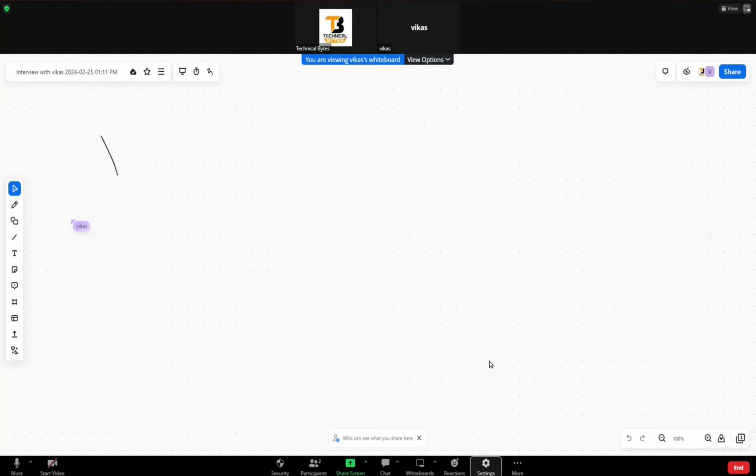In my counter, TCQ of the last flip flop and synchronization. Here the clock is coming here. And TCQ of the second flip flop as well as setup time of the second flip flop. Why are you considering setup time of the second flip flop? What is setup time of a flip flop?